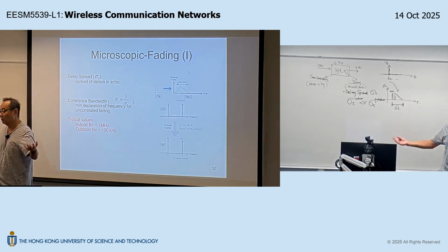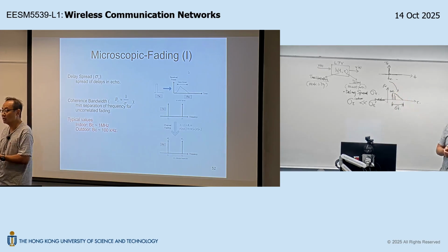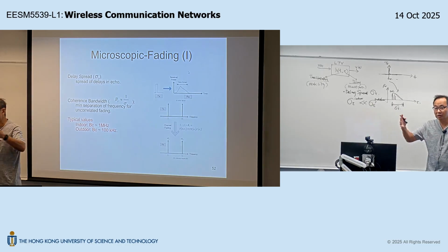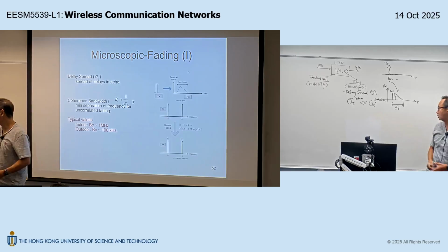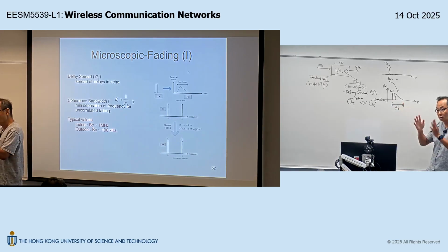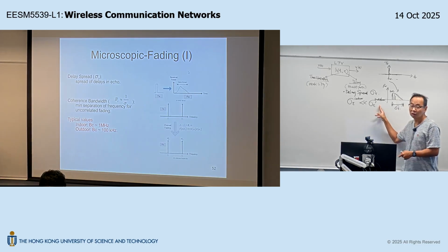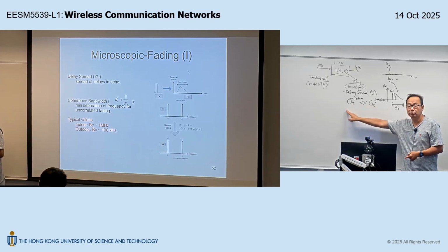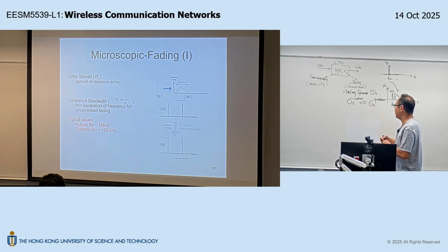The next arriving path may be reflection from the IAS building, let's say, okay? So you see, because in an outdoor situation, the scatterers exist over a larger dimension, the difference between the earliest path and the latest path, the spread, will be much larger. And that's the reason why, usually, in outdoor propagation the delay spread will be much larger than the delay spread for indoor.